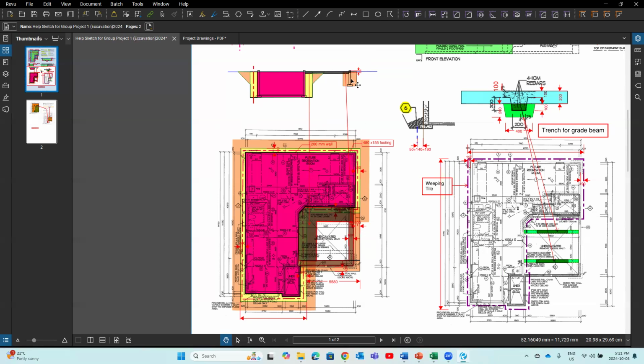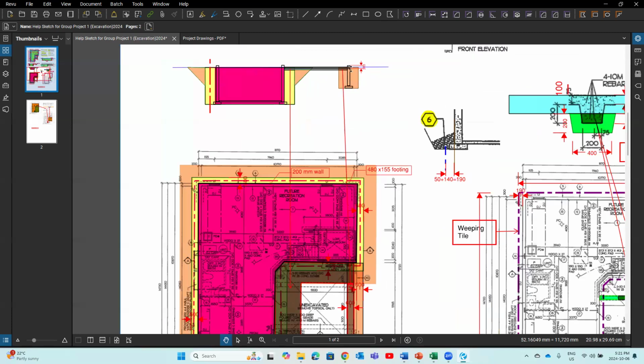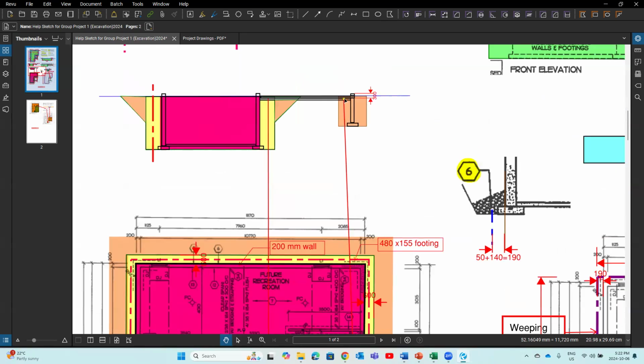So for trench backfill, you take the total volume of the excavation, subtract the volume occupied by footing and foundation wall in the trench, you get the backfill, right? What you need to pay more attention to is here, you see here? If we consider we backfill to the final grade, which is the existing grade, we need to think about inside of a garage. We only backfill to the bottom of the gravel, which is to this level. So if we calculate backfill up to the existing grade, we overestimate the volume, right?